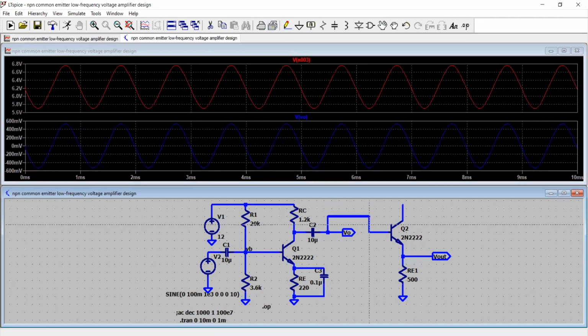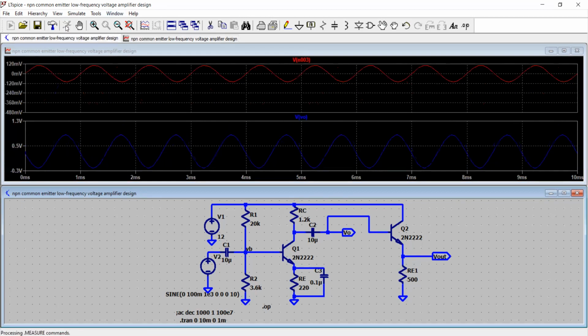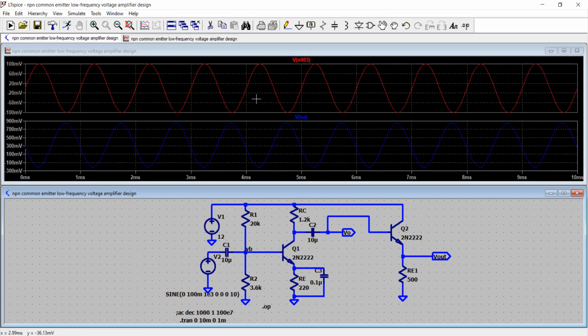So what you do is connect the output signal, then have a power supply to the second stage, run the simulation and look at that. This is how you can do that. You have a 0 volt DC bias level, then 100 millivolt, and the output here is about 300 millivolt, and it goes to minus 200. So from the 300 DC level you have like 800, so the gain is 5 times. So it makes sense, right?